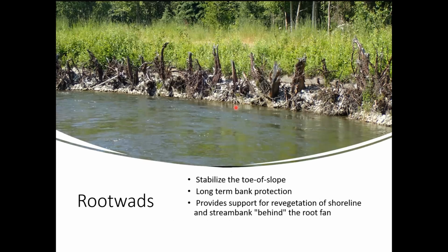In this picture, this is an anchorage along Campbell Creek. What we're doing is we've stabilized the toe of the slope. It's providing long-term protection because behind this is actually the Campbell Creek Trail. Really, root wads all they do is stabilize the toe, and then they provide a base for the vegetation to grow. As you can see here, we've got a brush layer on here, and you've got willows already starting to take off.